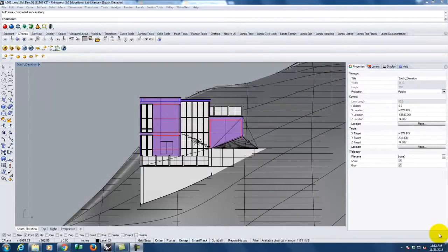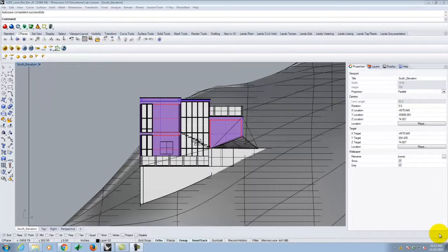So today we're going to work on cutting a plan from Rhino. This is very much the same as we did with our elevation view last class. We're doing virtually the same thing. The only thing that we are doing differently is we're adding a section cut. Instead of being in section view, it's going to be in plan view so we can look through the top of our building. So it's kind of a combination of the sections lecture that we did a couple lectures ago and the line drawing lecture that we did last class.